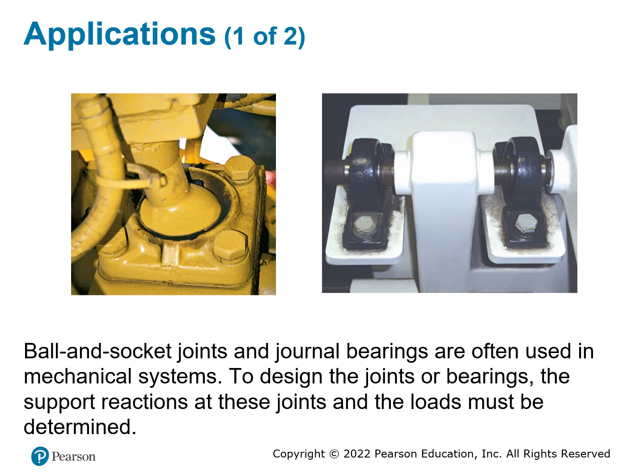So you will have a supporting force in this direction and this direction. This one prevents it from moving up and down, this one prevents it from moving left and right, but it can freely rotate. It can rotate without any other problem, and that is what we call a bearing.